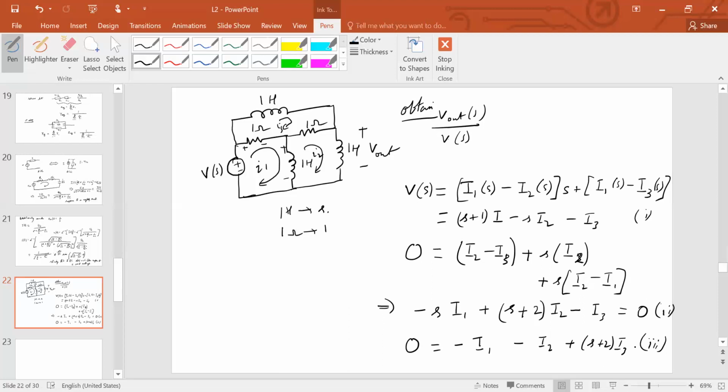All right. So having written down these equations, you can begin to notice the pattern here. The pattern is very simple. If you're considering your loop variables, your loop currents, in this fashion, you can straight away, even without application of much thought, write this in a very simple manner. How so? Just consider the applied voltage or the applied external forcing function on the left hand side of the equality.